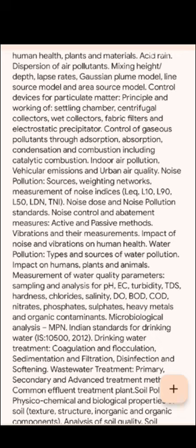Microbiological analysis, MPN. Indian Standards for Drinking Water, IS 10500, 2012. Drinking water treatment. Coagulation and flocculation, sedimentation and filtration, disinfection and softening. Wastewater treatment, primary, secondary and advanced treatment methods. Common effluent treatment plant, soil pollution, physico-chemical and biological properties of soil, texture, structure, inorganic and organic components.